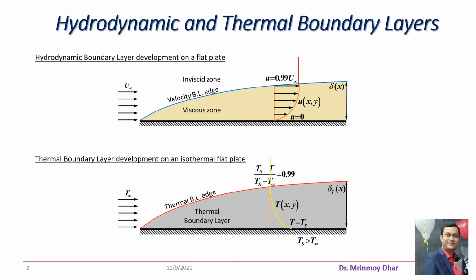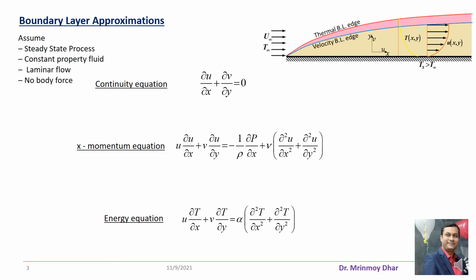With this introduction, we can move to the analysis of boundary layer flow. In the boundary layer flow, what we see is that these boundary layer flows are analyzed for finding out the velocity profile and temperature distribution. Then, if convective heat transfer is occurring, the convective heat transfer coefficient h and the Nusselt number. These are the objectives of analyzing boundary layer flow, to find ultimately these solutions of velocity and temperature.